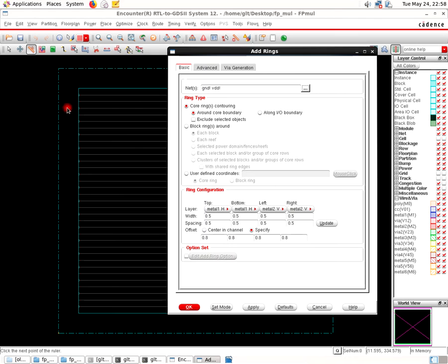In between that we have to add two power lines, one is VDD and another one is ground. So we can do one thing. 10 micrometer for one power line. Okay, the width of one power line will be 10 micrometer. So I'm assigning that 10 micrometer, and the spacing will be 5.